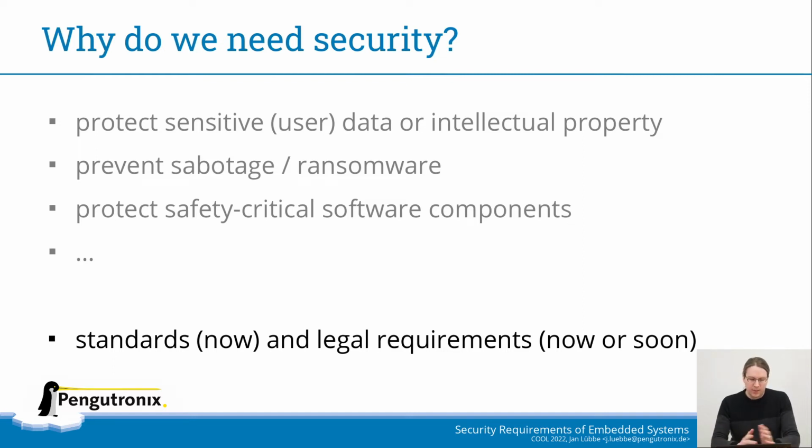So there's basically no longer any way around having robust security in our systems. And if you take a look at this standard, there's points about secure updates, secure communication, secure key storage. You have to minimize the attack surface by disabling network services and so on. You have to ensure software integrity, so things like secure boot. You have to have a process for handling security reports in a reasonable time frame. They give us 90 days as a guideline. So it's no longer as easy as it was 5 years ago, maybe.